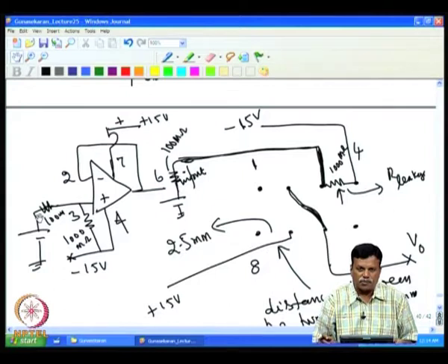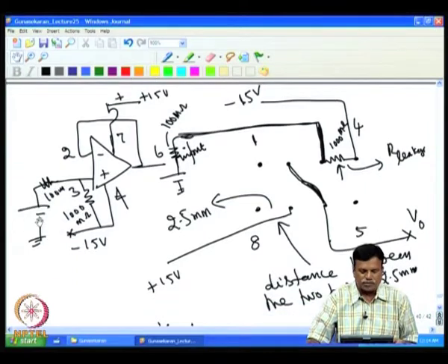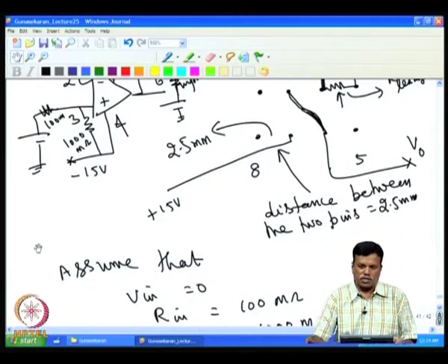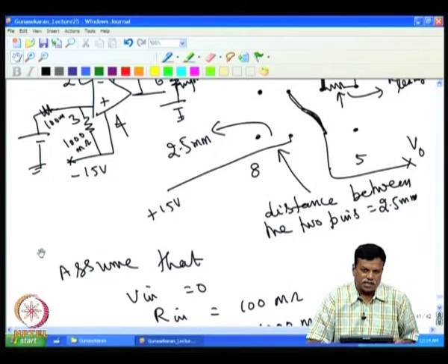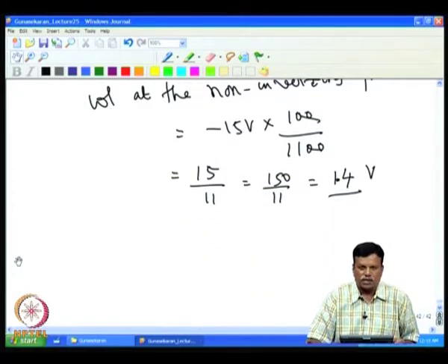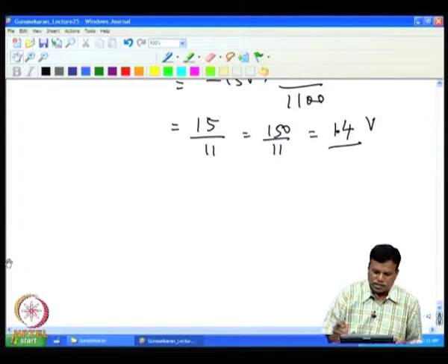This is a serious problem in high impedance circuits, because now we are dealing with a very high impedance, which is comparable with the PCB resistance. So, if I want to use high impedance circuits with high resistances, so that the voltage drop due to the bias current is less and the bias current effect is also less, then I have to go for some technique to remove this power supply leakage voltage that is coming because of the limited impedance of the PCB material.